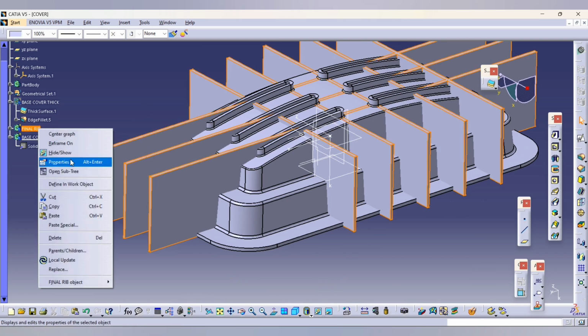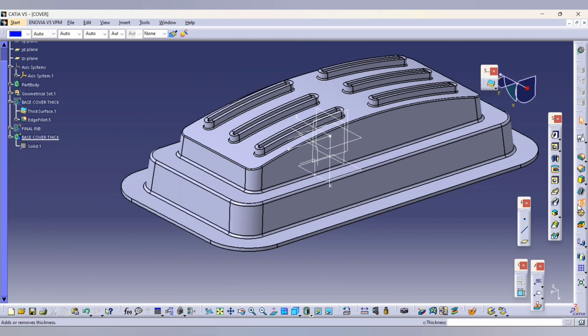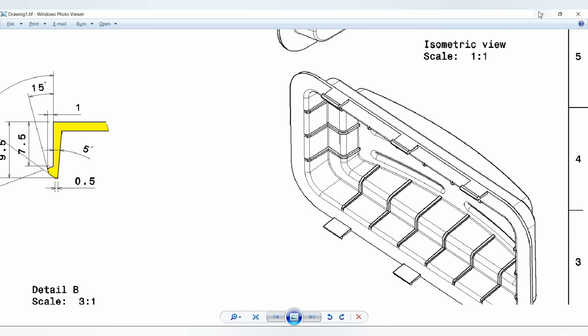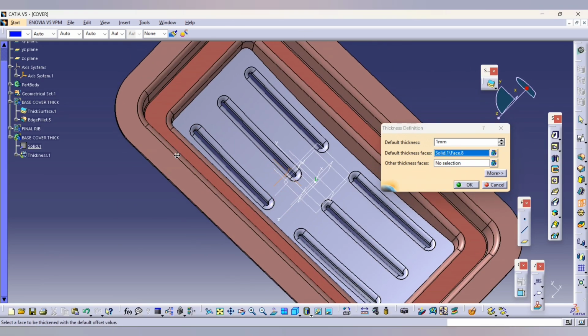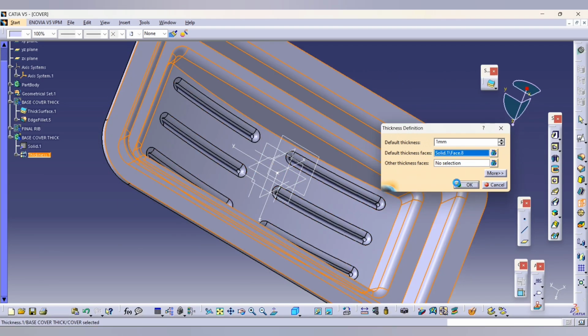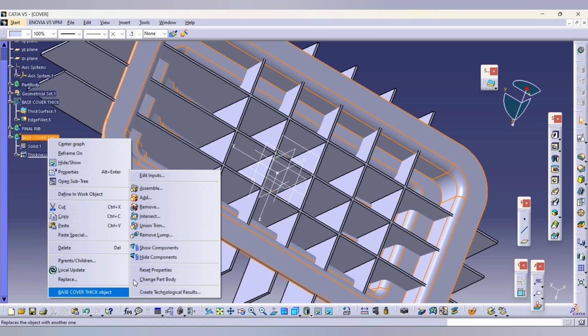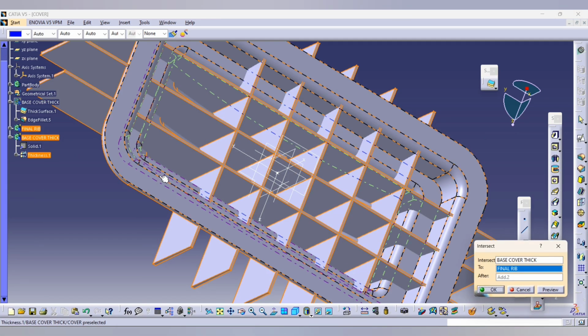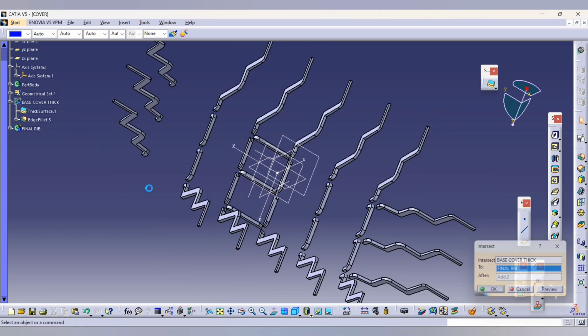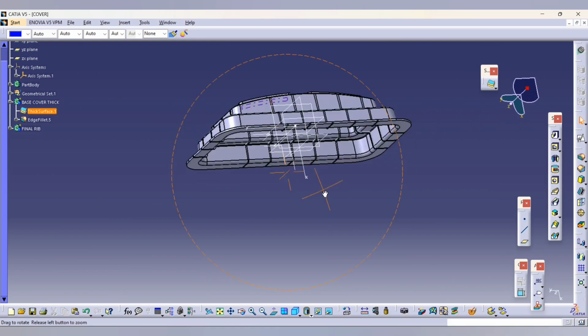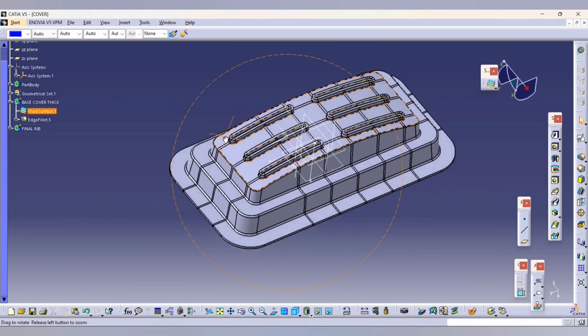So here we have to make an intersection so that we'll add the rib. So ribs are at inside, so maybe it is 1 rib. So we'll add a positive side thickness considering the inside area. So this is the inside area, and now we'll intersect this body with the rib body. So here the intersection of the ribs is completed with the 1 positive thickness from the inside, and here is